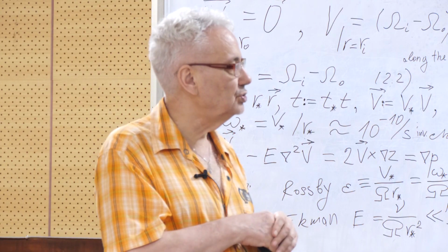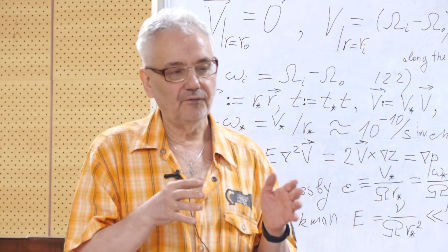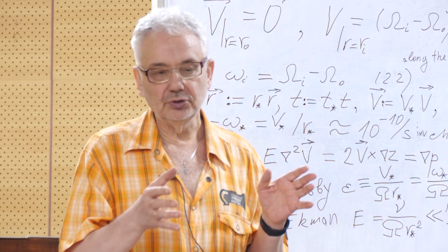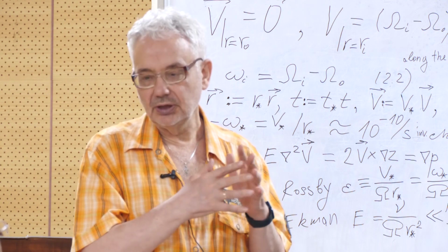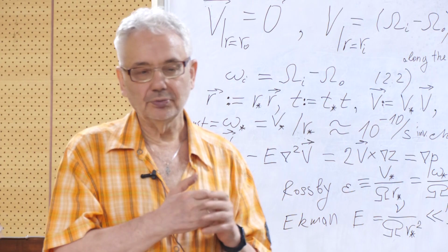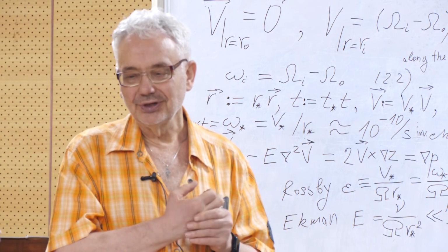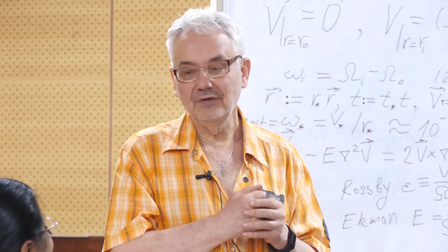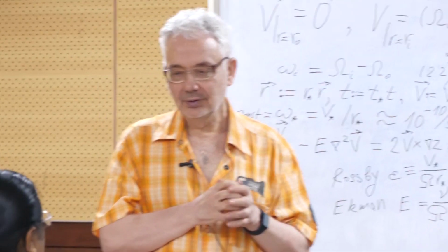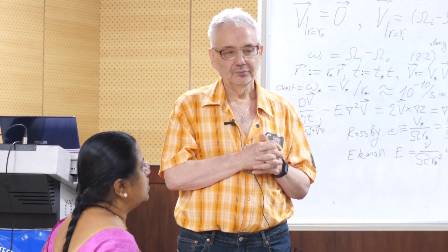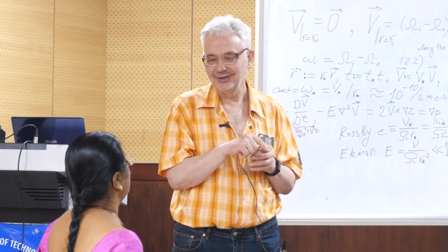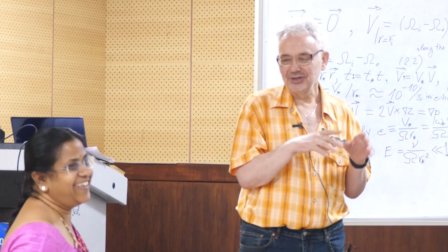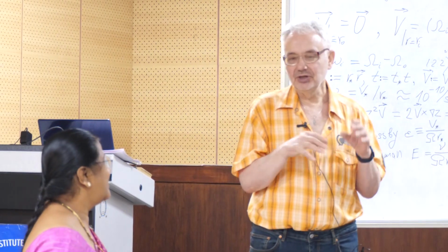So you reduce the problem, roughly say, from three-dimensional space to two-dimensional. You consider just boundary and shear layers, and you match them. So it's sort of the trick which allows to reach some asymptotic or even analytic solution, by reducing three dimensions to two dimensions. But eventually, even this two-dimensional problem is reduced to one dimension.